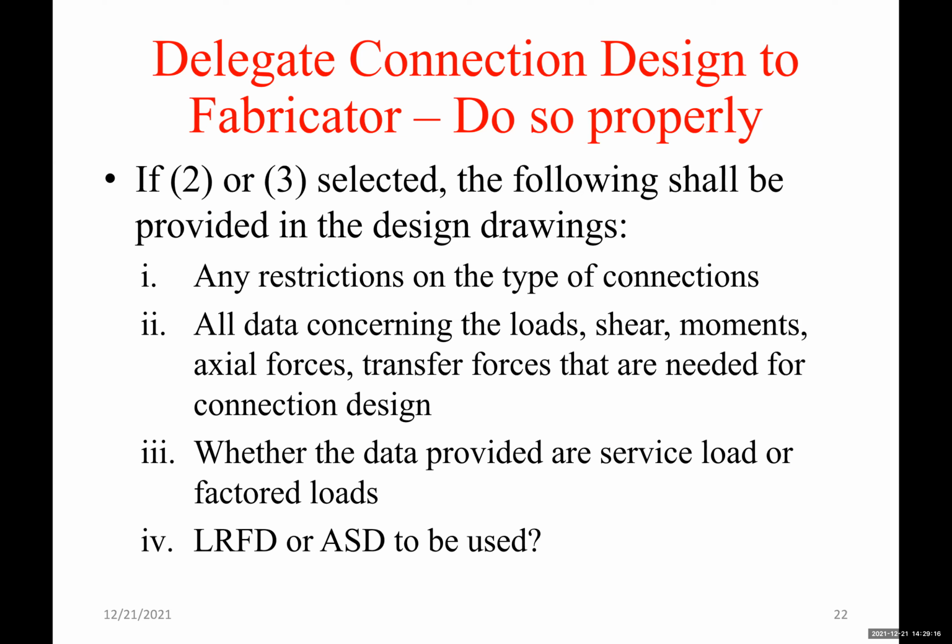Now, in the case of 2 or 3, where the connection design is delegated, the following shall be provided in the design drawings. Any restrictions on the type of connections, if there's any restriction by the structural engineer of record, should be shown. All data concerning the loads, shear, moments, axial forces, transfer forces that are needed for the connection design. Okay, we talked about that.